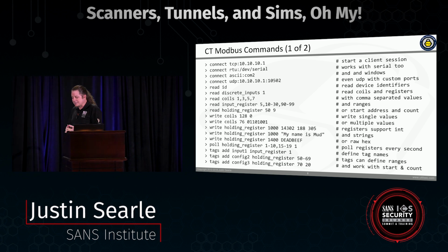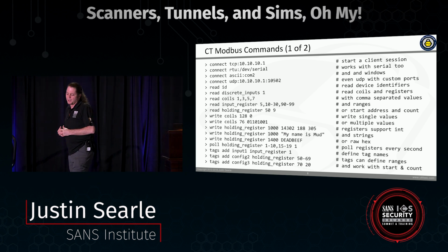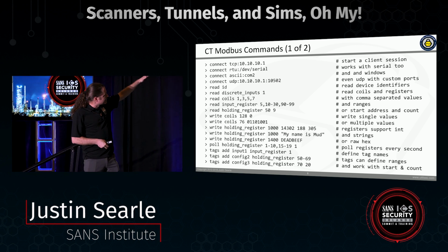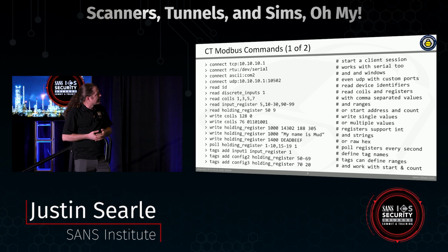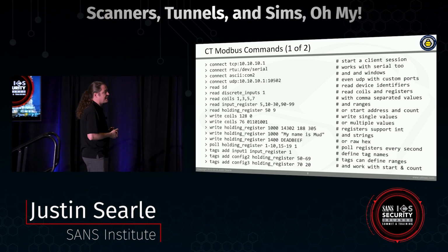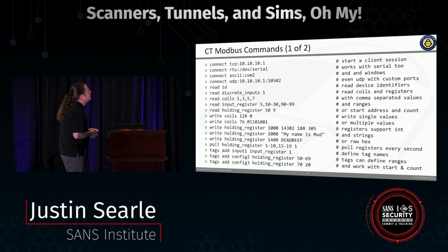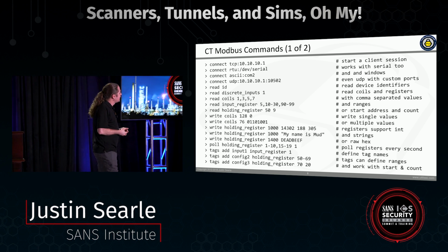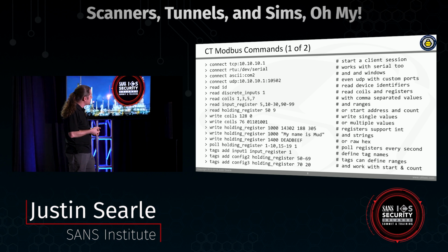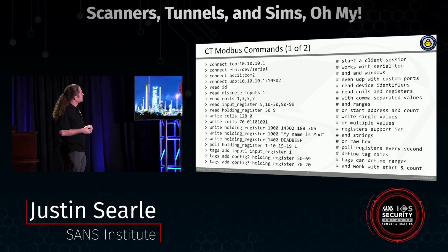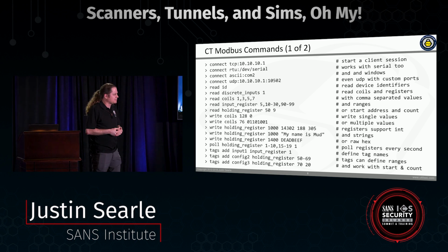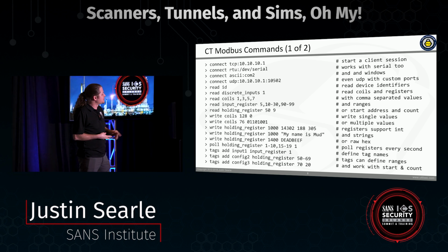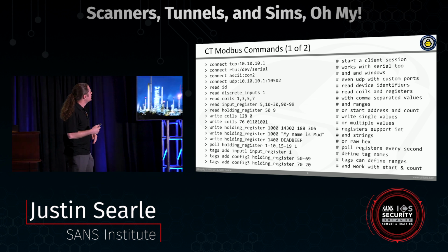To give you a little bit better idea of specifically the ctModbus tool, I have a beta version that's currently out online that you can go download. It has most of the features that are on this first slide. What you see here in these slides on the left-hand side is the command that you would actually type, with some different examples to give you some understanding of the flexibility on the inputs. A nice little description on the far right-hand side shows exactly what that command is doing. Notice that we can do individual tags, reading and writing of them, polling them, creating tag databases, or importing and exporting tag databases for Modbus devices through the device profiles.